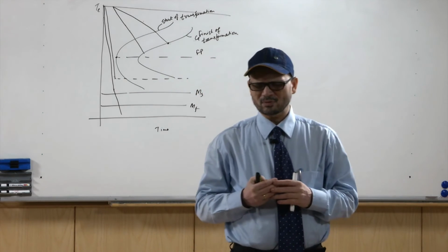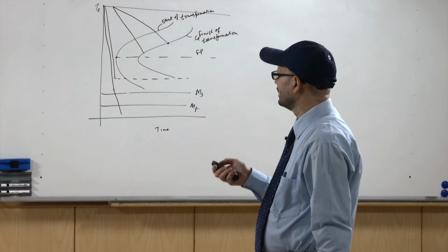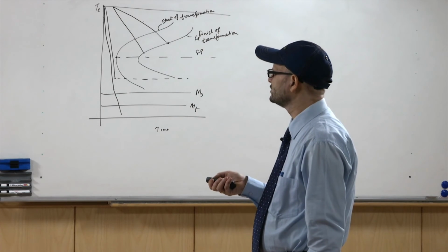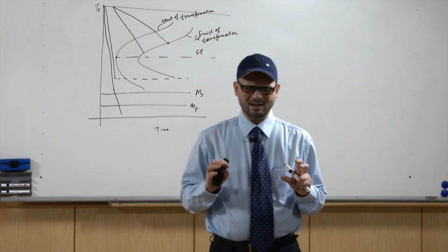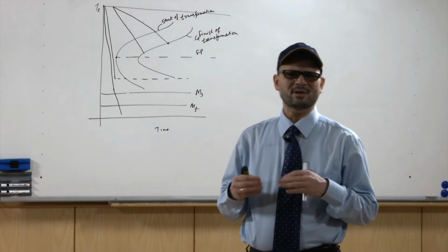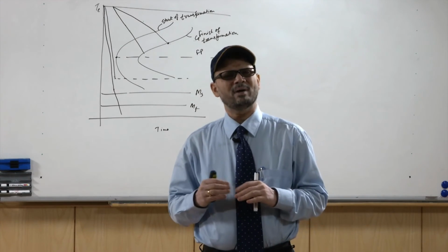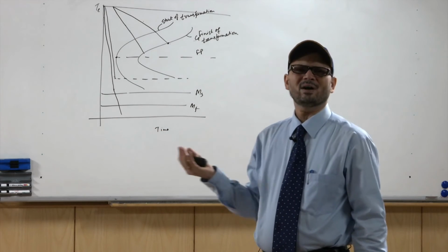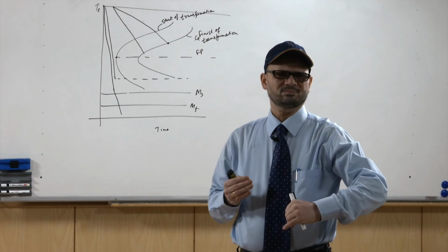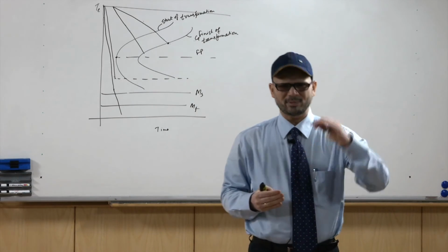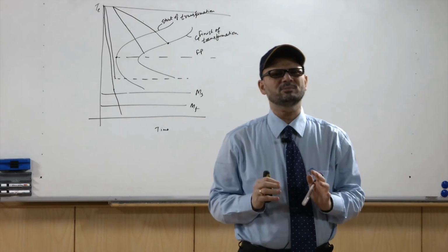The cooling rate is so fast that an extremely hard surface is achieved, and depending upon the section thickness, you will have the formation of hard phases like martensite up to a certain depth or the full section being martensitic. That again depends on what kind of TTT curve it is and what kind of cooling curve it is. Depending upon that you will have the formation of phases and a hard structure being formed.